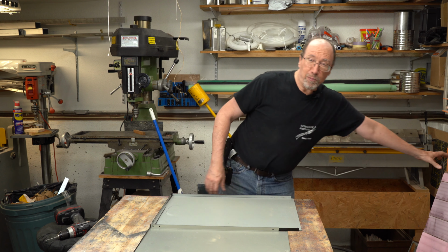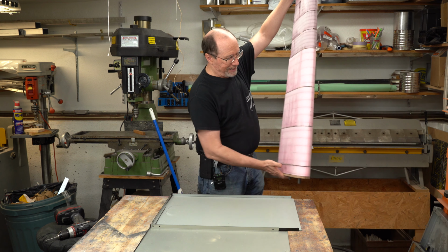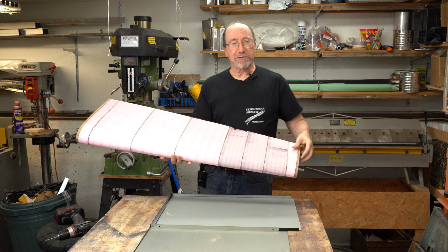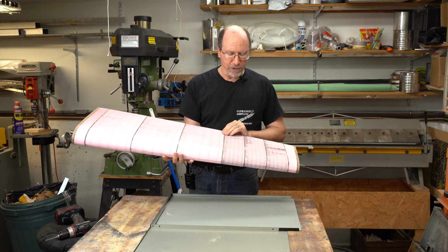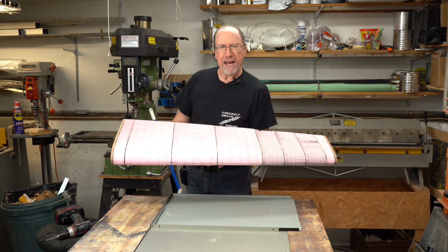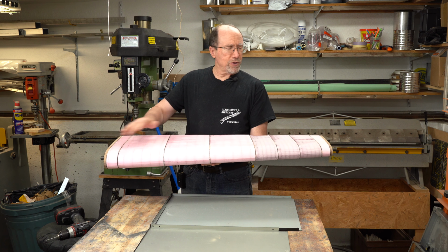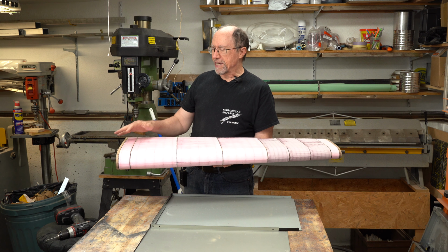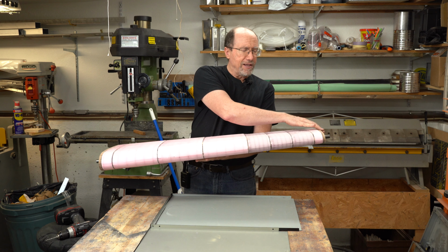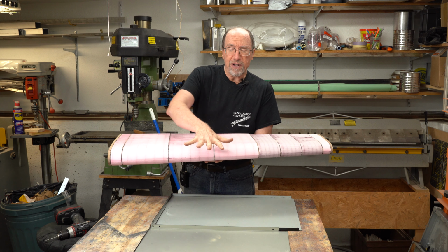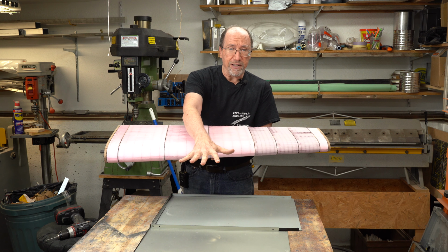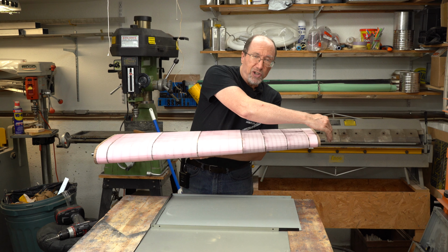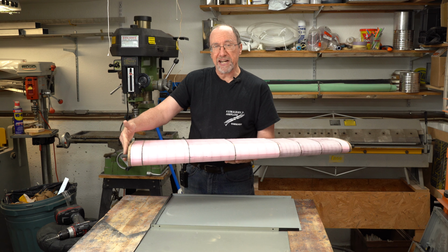Let me explain just a little bit more about what I'm talking about on span load and chord load. We got a little prop here that we can use. This was my first attempt at a plug for the UWS-1 Ultralight airplane rudders. So the span, of course, is going to be from a root out to a tip, and then if you're a wing, it's going to be even more. But for our tail, it's really just the root out at the tip. Now this is just the rudder, so there's going to be a vertical stabilizer in front of it, and the tip's going to go out just a little bit farther. The root is nearly the same on both.